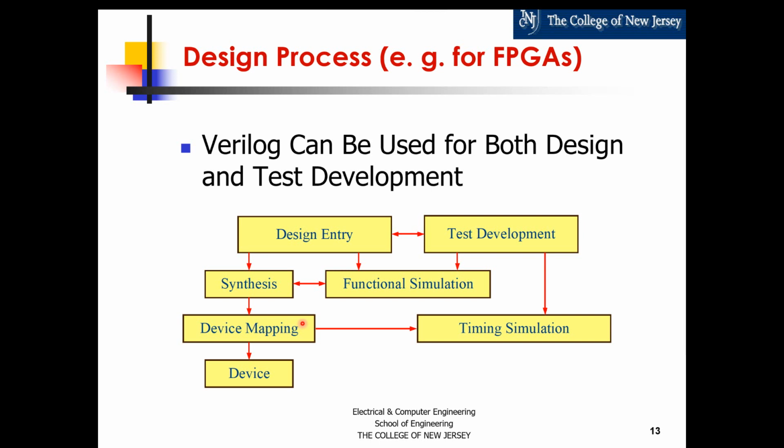And depending on the technology and the chip that has been fabricated, you are going to get actual timing that this design takes to run, to execute, to actually do its hardware job. And you can get timing data which you can use in a timing simulation, which is different from a functional simulation. The functional simulation step answers the question, does it do what I want it to do? The timing simulation answers the question, does it do it with the level of performance that I want?